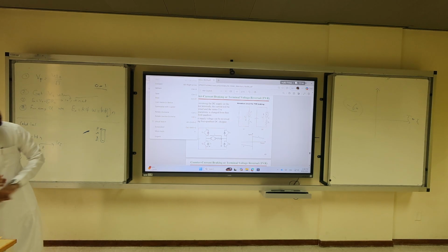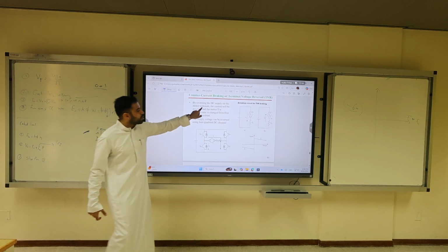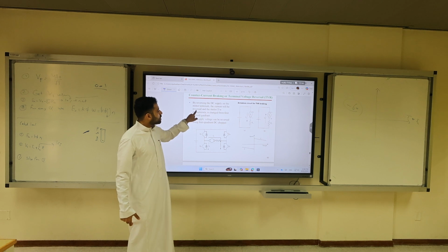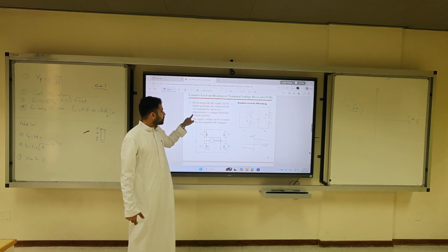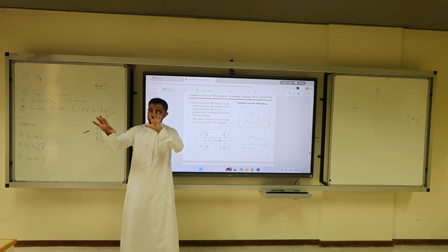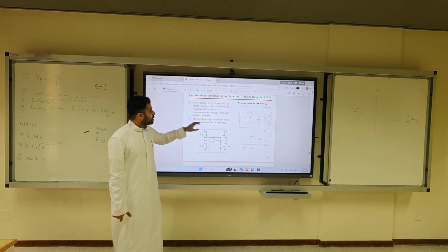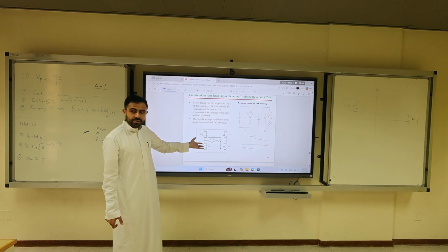Here, the counter current is done by reversing a DC supply on the motor terminals. The current will be reversed and the motor torque speed characteristics are changed from first to third quadrant, which is both torque and speed negative. The supply voltage can be reversed using, for example, a chopper.